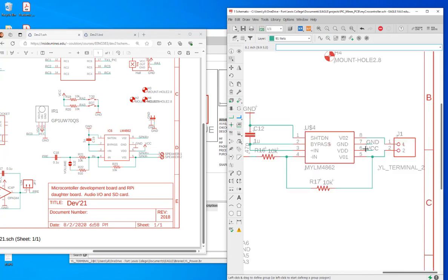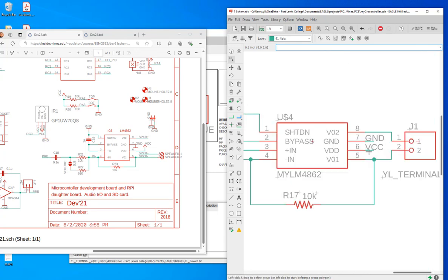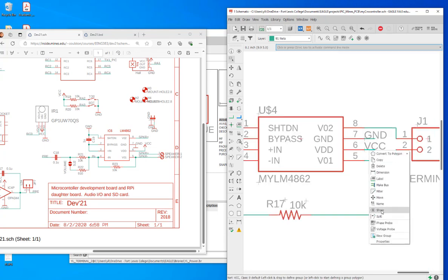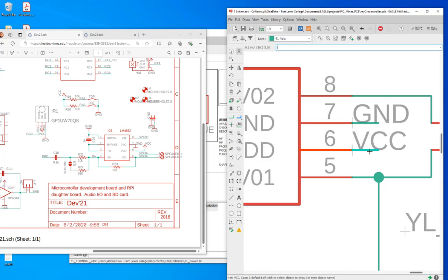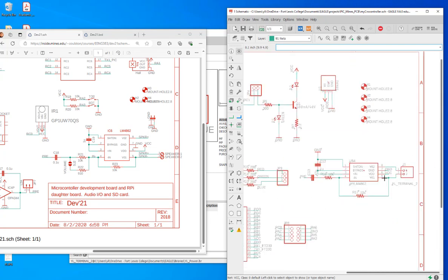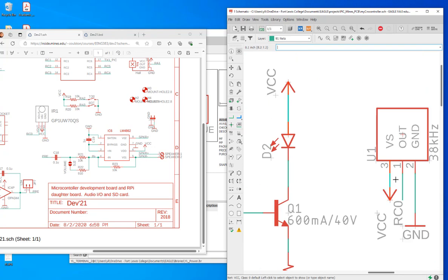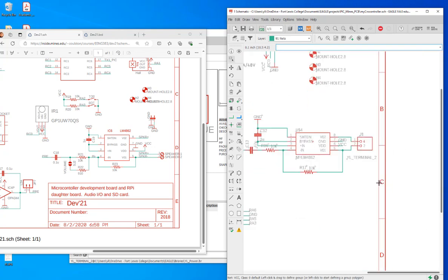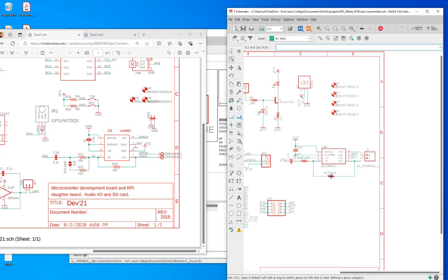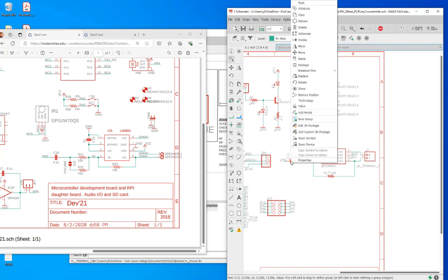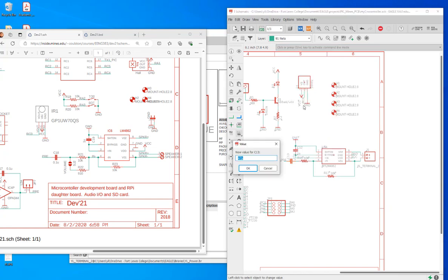And you can try to highlight it, see if they are shorted together. So ground is definitely shorted, but this one, let's right click and do show. You can see the color becomes different. And let's see if we can tell. Okay, so this is getting highlighted, which means it's shorted to VCC, no problem. Okay, this one, 10K, speaker plus, speaker minus. We don't need to know that. Oh, this value hasn't been changed yet, so this value should be 0.1 micro.